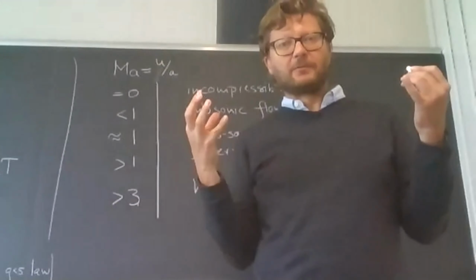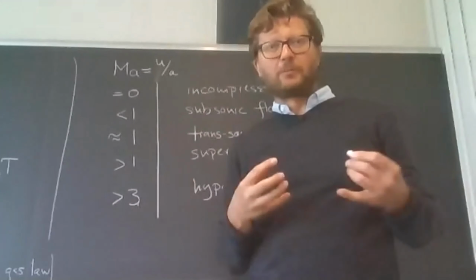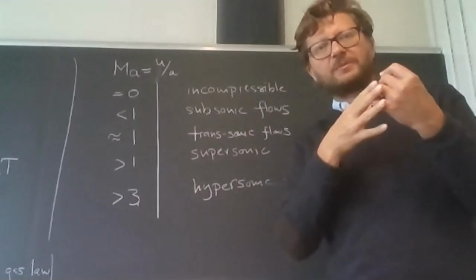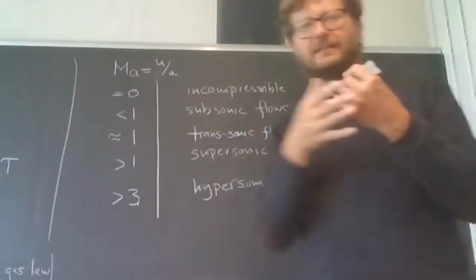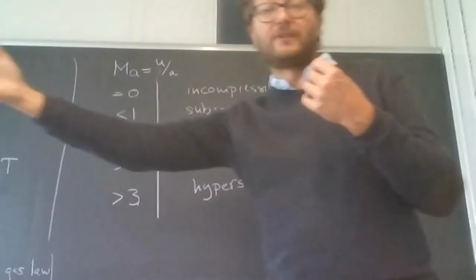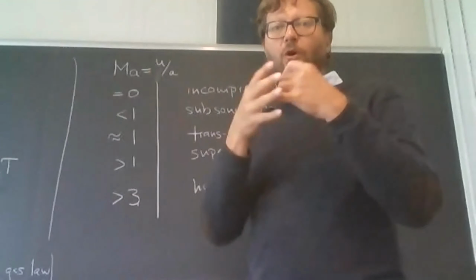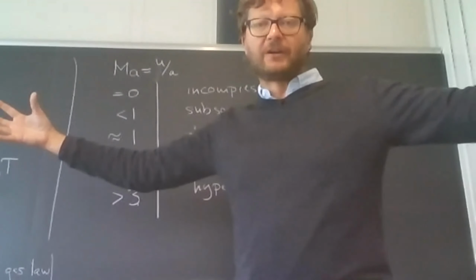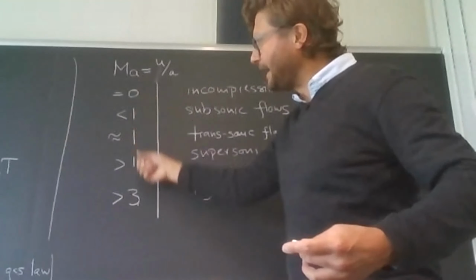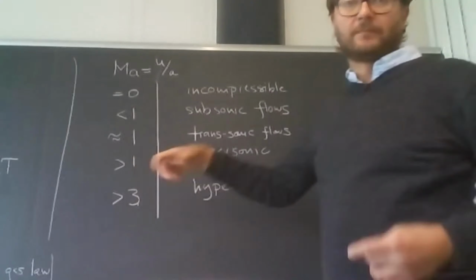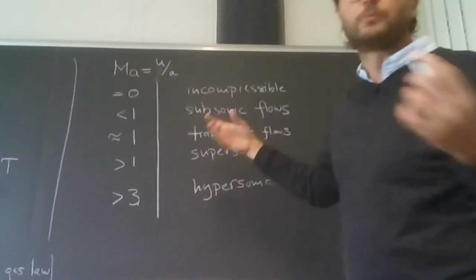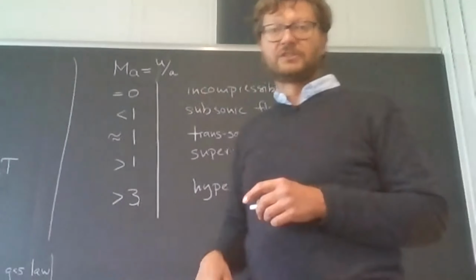So incompressible flow, in the language of compressible flows, actually means that we have a flow where the speed of sound is so fast that all information is propagated at infinite wave speed. So all information is immediately everywhere, and then we have incompressible flow. Wherever we have finite speed of sound, we are either in subsonic or in supersonic or hypersonic flow conditions.